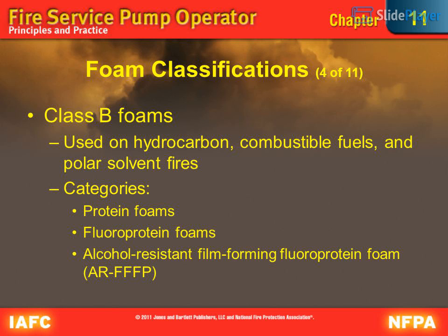Foam classifications, 4 of 11. Class B foams. Used on hydrocarbon, combustible fuels, and polar solvent fires. Categories: protein foams, fluoroprotein foams, and alcohol-resistant film-forming fluoroprotein foam, AR-FFFP.